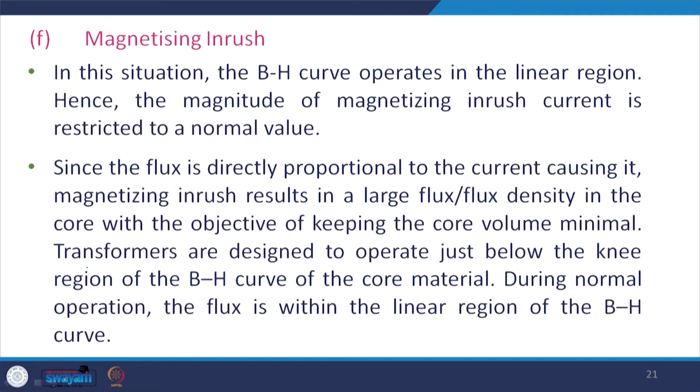Now, in this situation, as the flux is symmetrical in nature, the operating point always stays in the linear region of the BH curve, and hence the magnitude of inrush current is restricted to a small value.